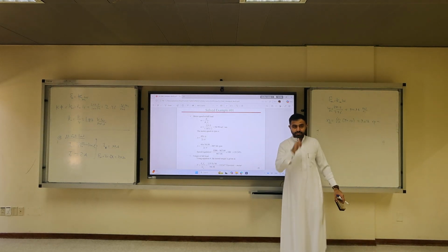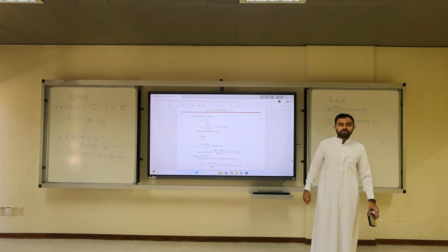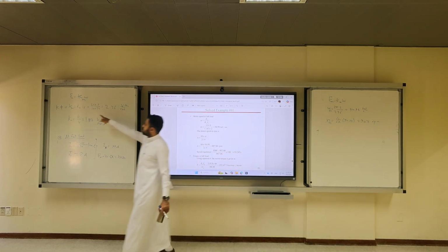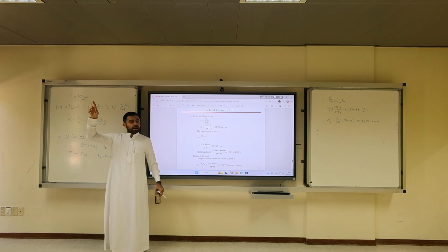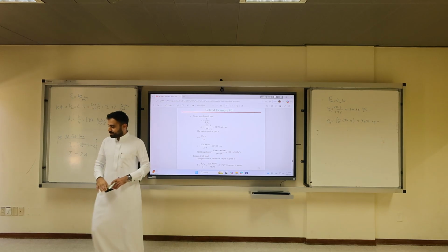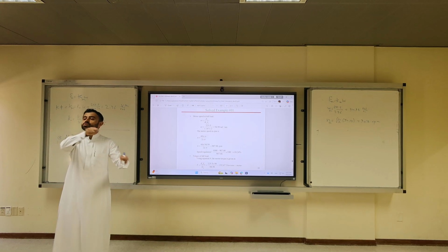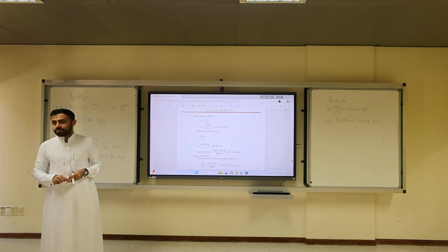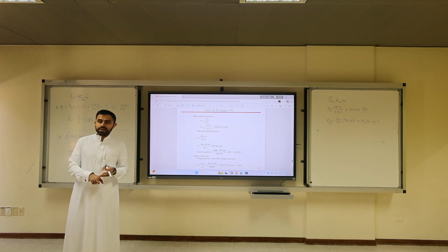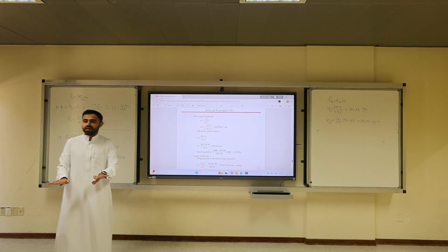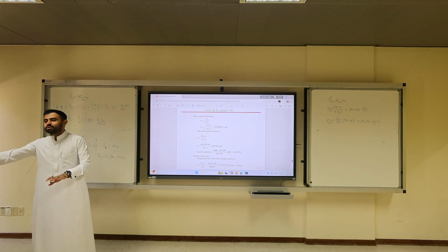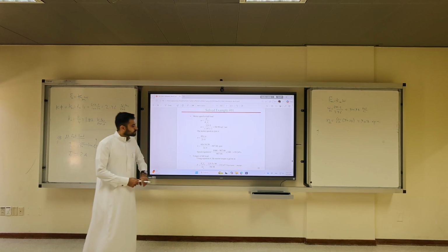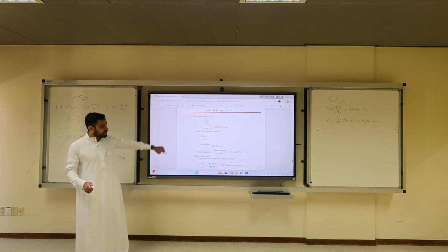Yes? It is always 2. Why 2? 1.87 times 2, because the field current, but I named this Km. The field is 2, it's written in the statement. Okay, but the field is usually constant, no matter what, if it's shunt. In shunt, is there an IF in series? No. In separately excited, the field is usually assumed to be constant. But in this course for 362 we will have examples where we change the field. What will happen if we change the field? Speed will change. In 360 we did not change, so this is 360 still.